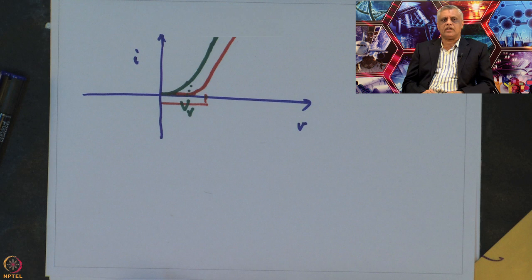While looking at the IV characteristics of the diodes, it is important to note that even though the cut-in potential, or the threshold potential or the contact potential of the device, may be given by a standard constant value as we discussed in lecture 8, the actual voltage drop across the device may be higher, something like 1.5 volts or even 2 volts due to the ohmic property of the device. Hence, it is important that we do not confuse the cut-in potential or the contact potential values with the actual voltage drop across the device.